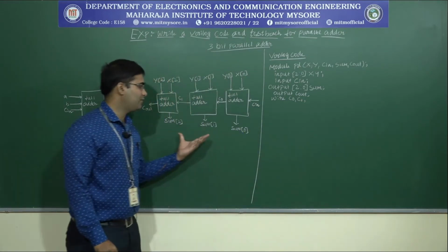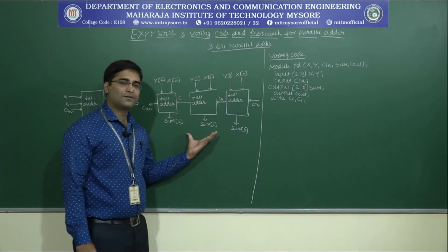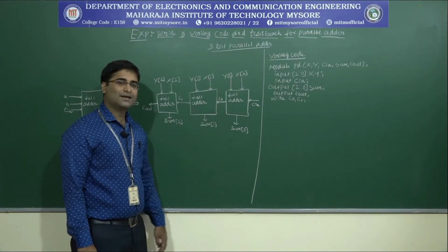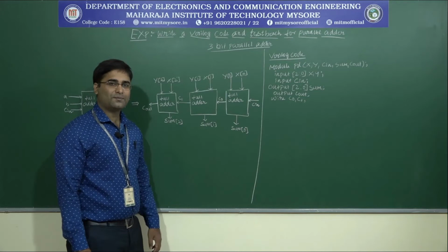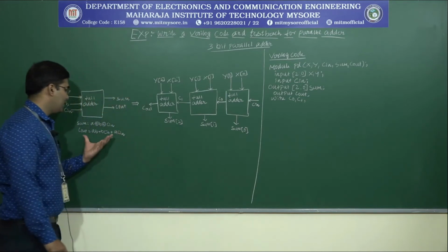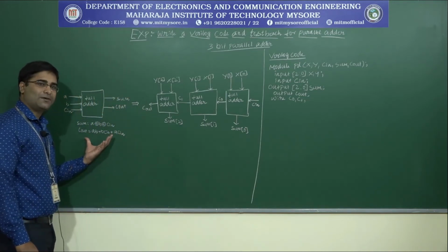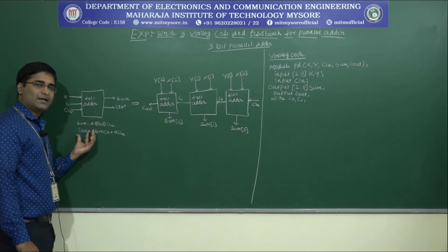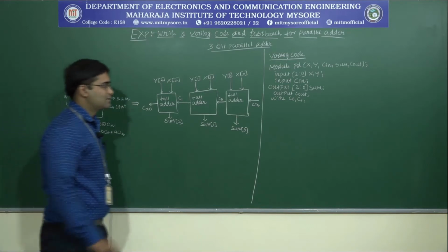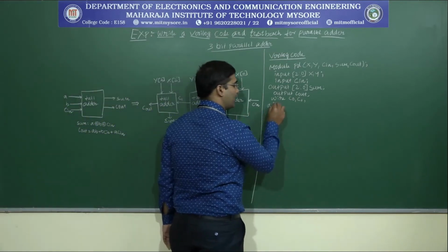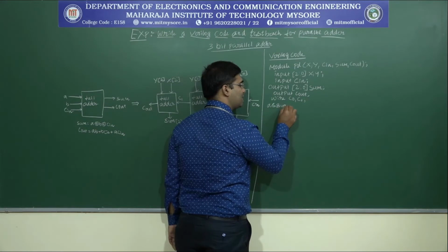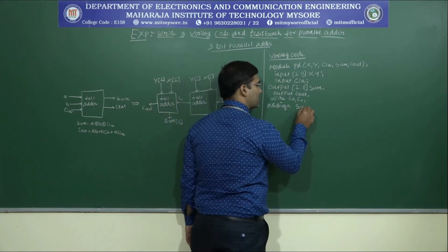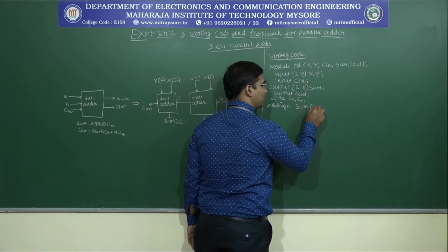Next we will define the sum for the full adders, and next the carry out of the particular full adder using the expression that we have defined for the full adder, which is for the sum and the carry out. So we are using an assignment statement, a predefined word which is assign, sum.